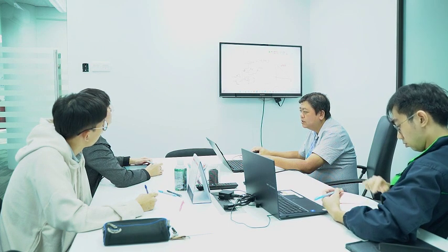At the end it becomes minus 40 dB per decade. This one is minus 20, and this other one is another minus 20, so the slope becomes minus 40. That means you have one origin pole plus one normal pole. This one I call a normal pole, and this 1 over S you can call an integrator.